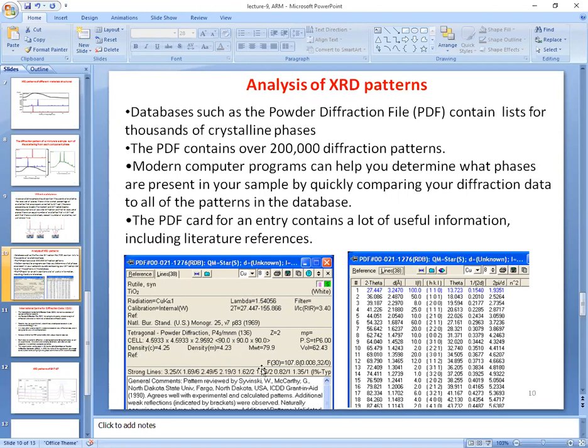Similarly, the density and a lot of information about the crystalline material. This is basically the qualitative, and also the quantitative description of the data. And this is the quantitative data. In fact, this is the 2 theta values. This is the d-spacing, and this is the intensity. This is the HKL, the Miller indices planes from which these peaks are obtained, and this is the theta.